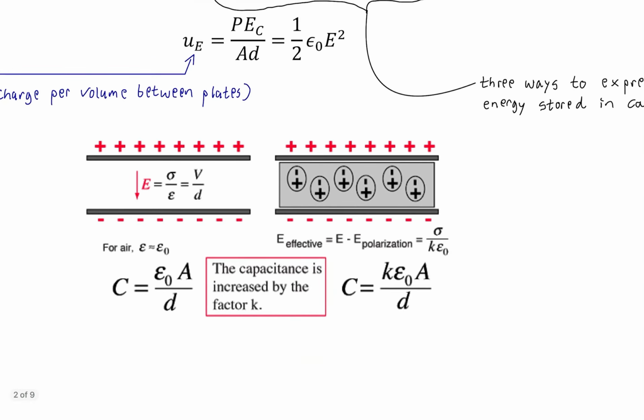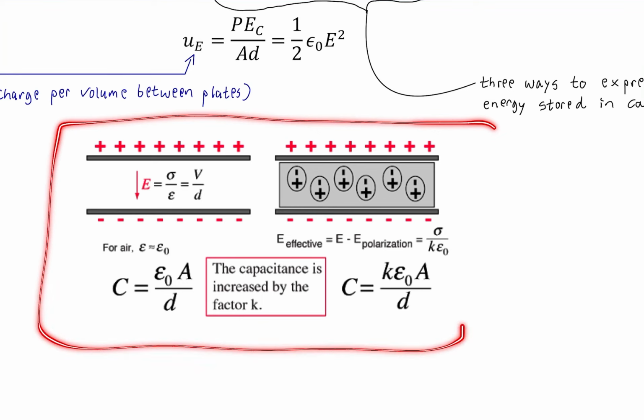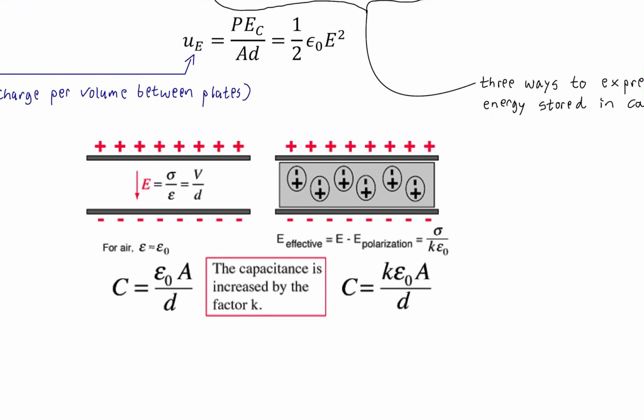So here we have the dielectric. This is a similar figure to the one on the previous page, showing the dipoles that exist in the insulator that create that opposing electric field. But here's the actual equation. Here is the capacitance that we saw above, without a dielectric, and here's the capacitance with the dielectric. There's the dielectric value, the dimensionless value K. You look it up, like a dielectric of 5, 1.2, or 20. Just a number, and it's empirically determined. They've done experiments with these materials and found out how good they are at creating these opposing fields, and thus increasing the effective capacitance of the capacitor.